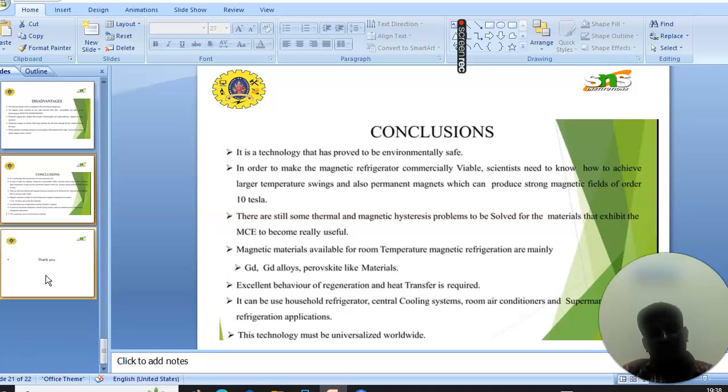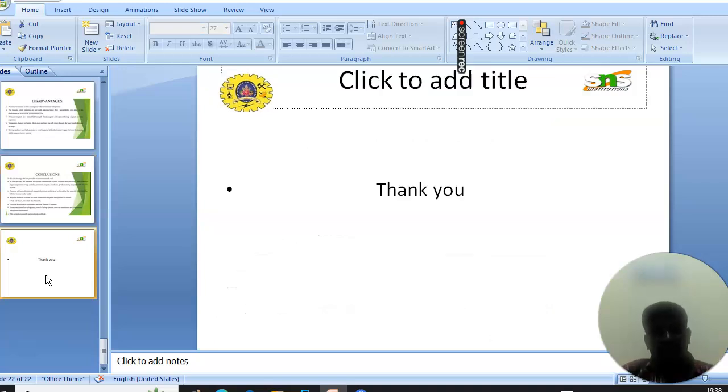The magnetocaloric materials are rare materials, hence their unavailability also adds to the disadvantages. Permanent magnets have limited field strength. Temperature changes are limited. Multi-stage machines lose efficiency through heat transfer between the stages. Moving machines need high precision to avoid magnetic field reduction due to gaps between the magnets and the magnetocaloric material.